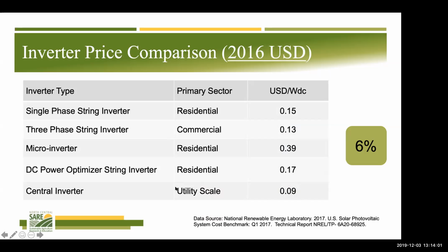So, we looked at the breakdown earlier and saw that 6% of the total installation cost was related to inverters, and John shared with us a number of different types of inverter technologies that we might consider for a number of different reasons. Part of it could be simplicity purposes in terms of installation. Part of it could be related to trying to qualify or be in compliance with Article 690.12 of the rapid shutdown standard, or it could simply be shading issues. So the reasoning for these different